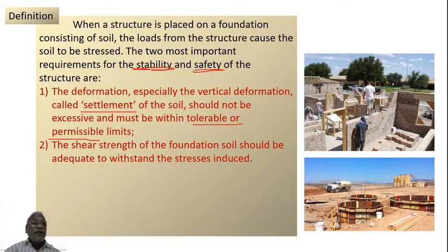So that's why the two factors we should worry about are, if at all there is a settlement, how much is that, and whether the foundation is going to withstand the load coming on it. One tells about the stability, another tells about the safety, and while designing the foundation you have to take care of both.